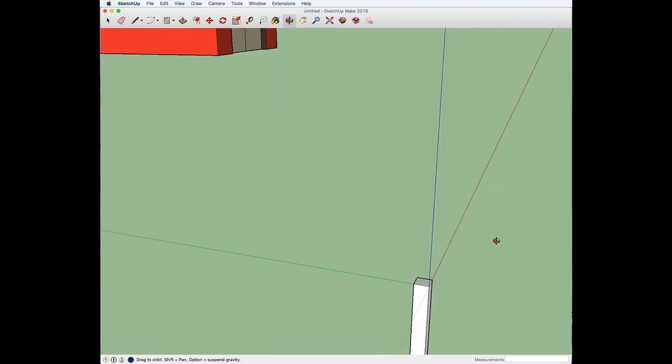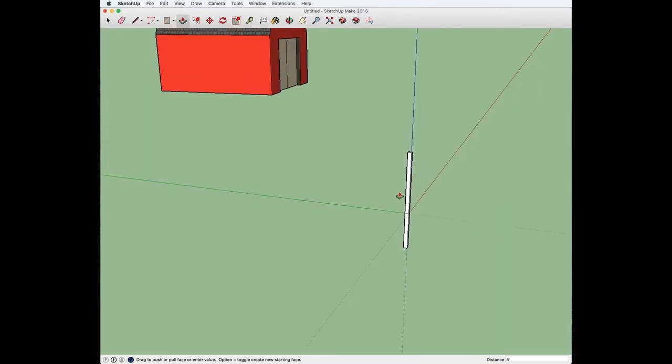We're going to purchase an 8-foot post, so let's raise this post up 5 feet above the ground. We click the top of it, raise it up, and press 5, single quote, enter. Now we have our post. Now, let's say we want these posts 8 feet apart. We could sit here and draw each one of those like we just did, but that's kind of a waste.